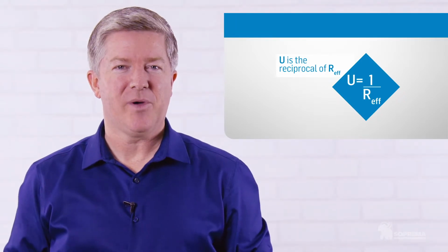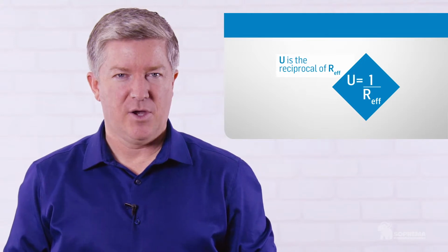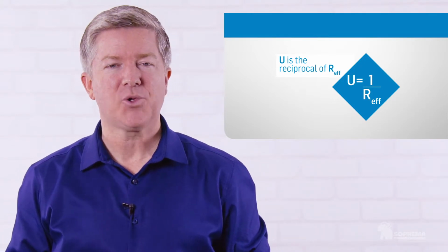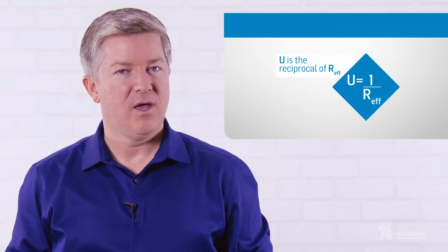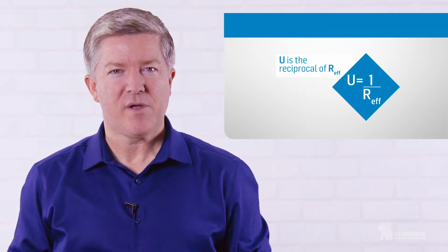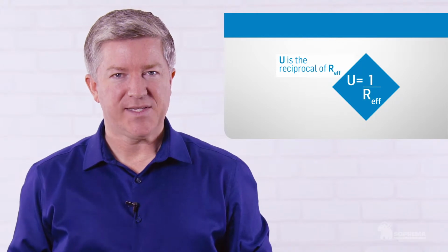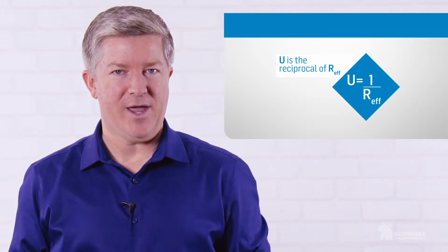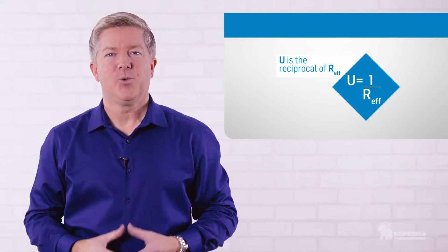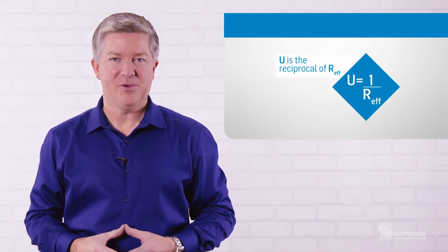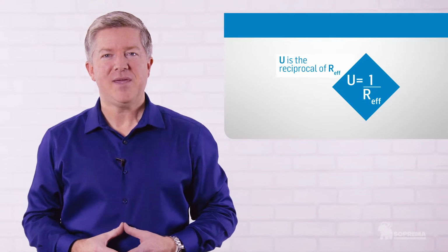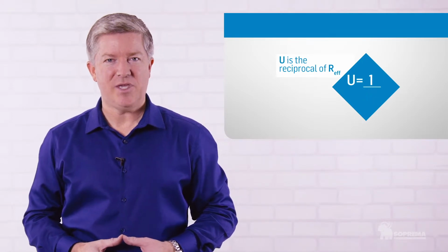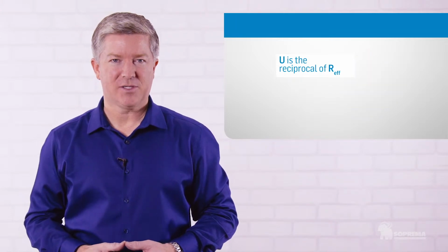We're used to talking about the R value of materials. For example, an insulation material may have a thermal resistance of R20 or R25. The higher the R value, the more efficient the material. For an assembly, performance is linked to U value, which goes the other way. Like when we play golf, we must shoot low for U value. The lowest U value means that the assembly is the most thermally efficient. NECB requires maximum U values.